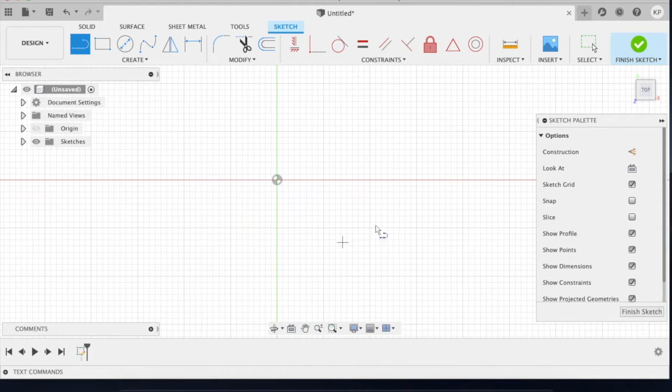You've probably figured this out already, but you can actually sketch anywhere in here. You don't have to start at this center point. We're going to use any point of this to create our sketch, and it really doesn't matter the size, just keep it around 5 inches or so. We're going to dimension these later. When you go up for this one, just make sure that you're snapping to get those 90-degree angles. We're not really concerned about any sizes, just try and match my shape.